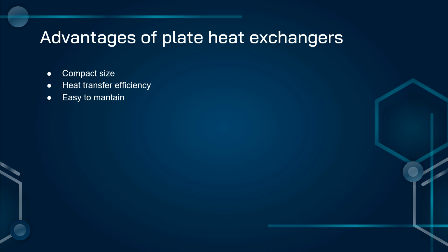Also, another advantage is that it has higher heat transfer efficiency. The large surface area of the plate ensures faster and more efficient heat transfer, and also it is easy to maintain. Why? Because the plates can be easily removed to be cleaned, repaired, or maintained.